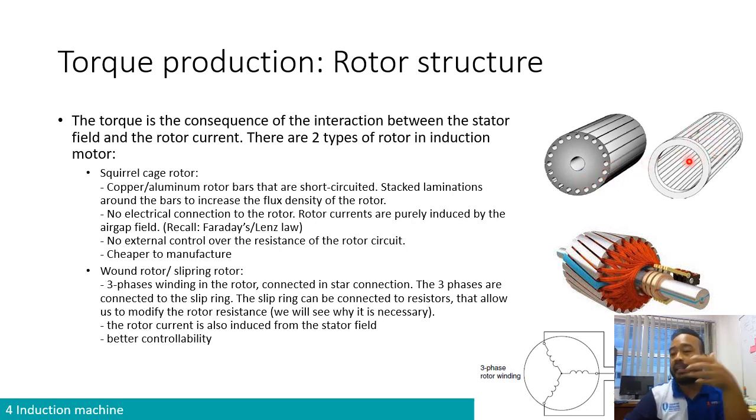So what's going to happen later, as you can probably guess, there will be current that is generated and circulating inside what we call the cage over here, and therefore there will be a magnetic flux around it, and we add this lamination to intensify and to properly conduct those fluxes to increase the strength of the flux, right?